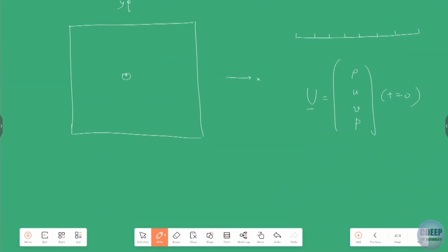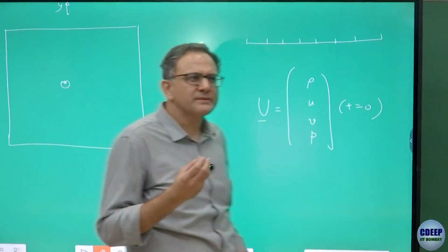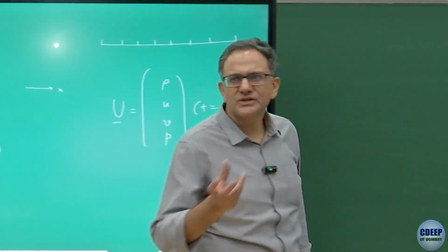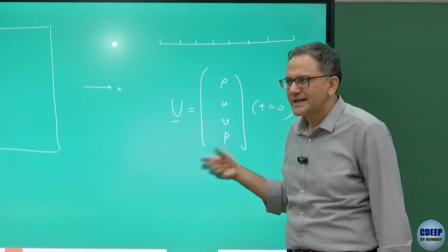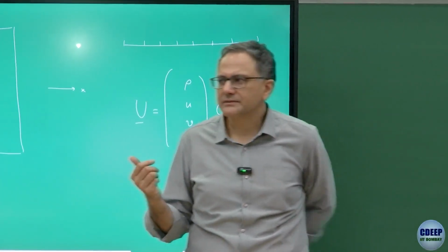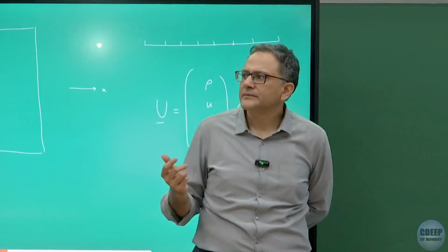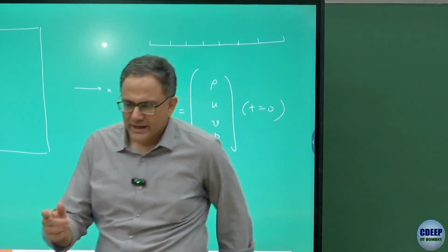This fluctuation, that is my sneezing, is it all irrotational, is it all isentropic? I wouldn't be able to sneeze irrotationally. I will create these vortices. So there will be vortical disturbances, and if I am very charged up, there will also be some entropy that I will be generating. So there is some entropy and vorticity disturbance along with the acoustic. How will they travel? How do you know that they will travel? You know how the vorticity travels.